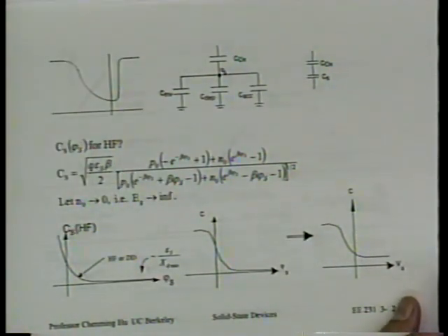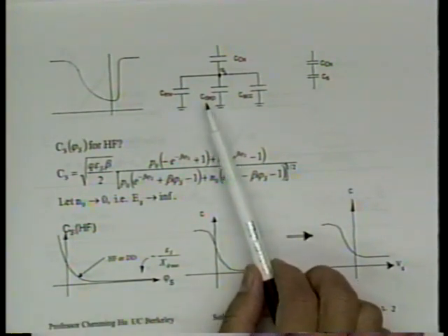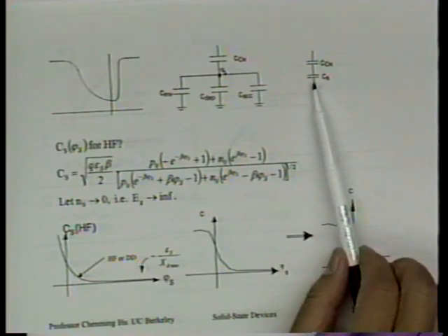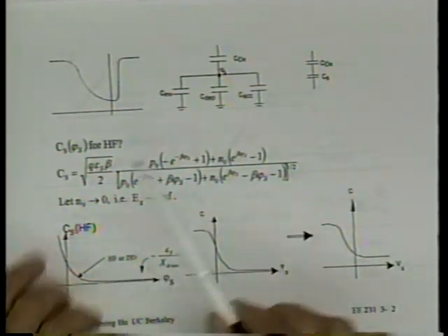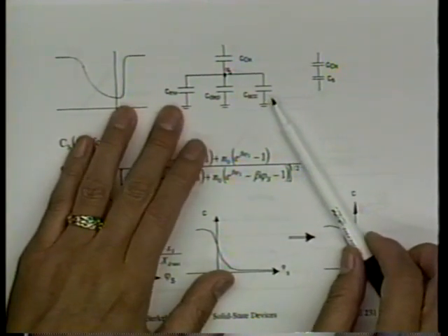Good. This diagram, the next slide, is something you have seen. I just want you to remember again that this capacitance is made of three parts. There's inversion capacitance, depletion capacitance, accumulation capacitance. Altogether, we call that CS, and CS is in series with Cox. The inversion capacitance and accumulation capacitance, usually we don't have to carry both of them.